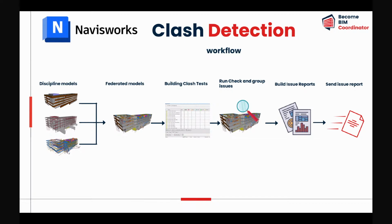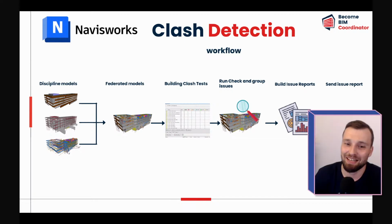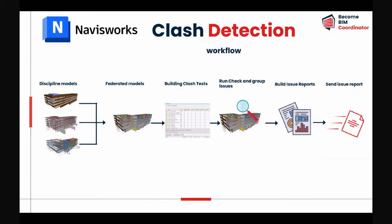The first step is to create clash tests that will, let's say, dictate what we want to check. Then using these tests, we check the model. And once we have all the issues, all the clashes that Navis found, we need to group them in a meaningful way. Then we generate a report of these issues, called an issue report. And at the end, we send this report to the people responsible for fixing these errors.